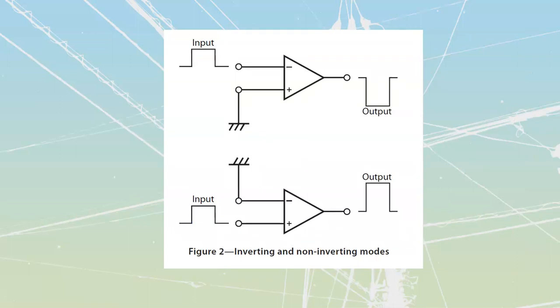And that's all we would be doing over here: we're going to take this lead and tie it to chassis, or to my 0 volts. Which means that in reference to that 0 volts, if I take in any value of voltage along my inverting lead, it is seen as a positive value of voltage, so it's going to multiply it by a negative gain. It is going to switch to the negative out, and it's going to drop my total amount of output.